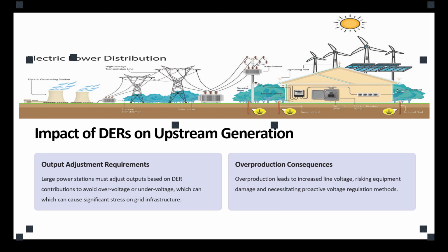If we cannot adjust the power or the power flow precisely and in a stable way with the bulk grid, what's going to happen? Either we are low in generation compared to the demand, which in active power means the frequency would fall. You remember that relation? And in reactive power it means the voltage will fall. This is one scenario.